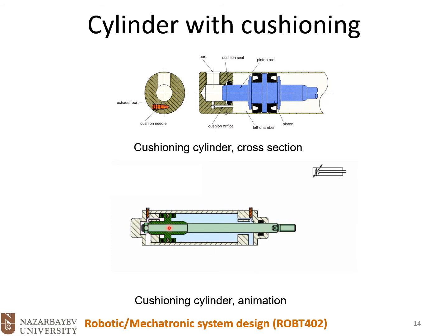So that small chamber creates some cushioning. Why? Because the air itself is compressible, and the compressed air inside this small chamber at the beginning and end will decelerate the piston, and the piston mostly stops at the beginning and end.